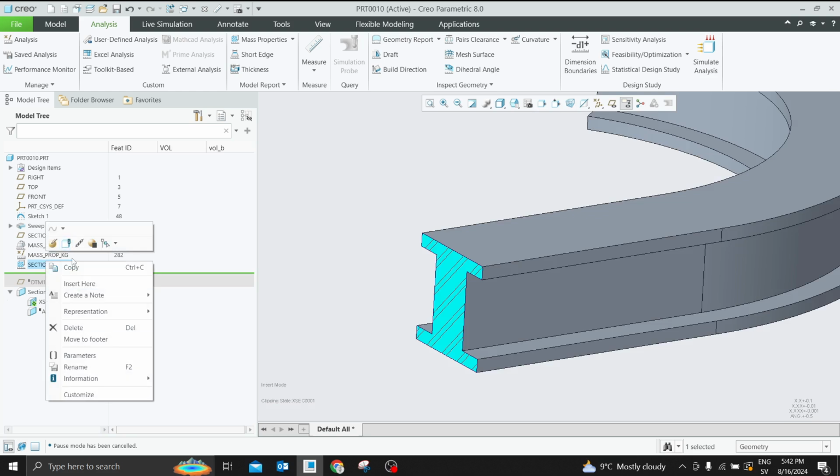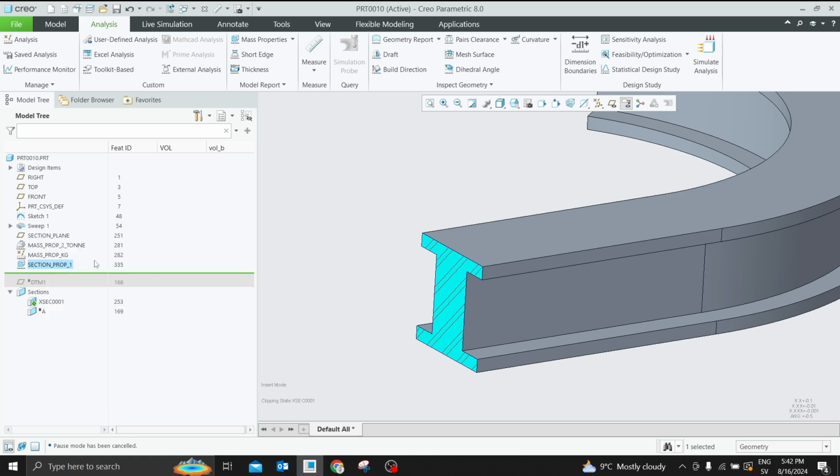This is what I'm using here. You can get it from this icon here. You can just go to the information. I'm using feature information, in case you are wondering where this icon is. Then from there, I have the mass in kilograms, and I have the principal inertia, that is maximum. I want to maximize this and reduce mass.